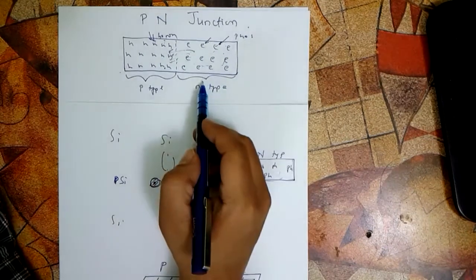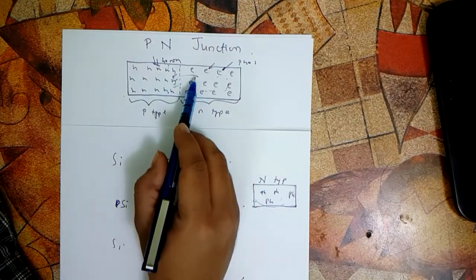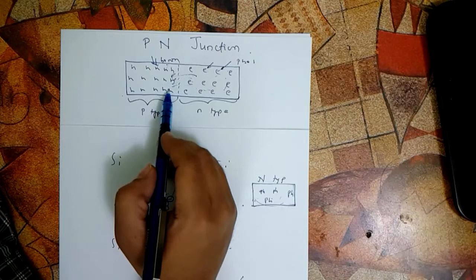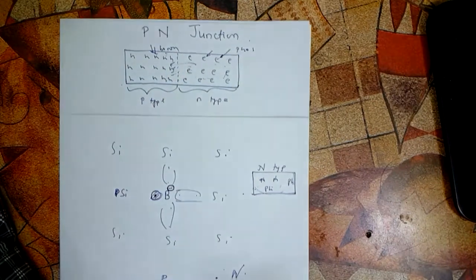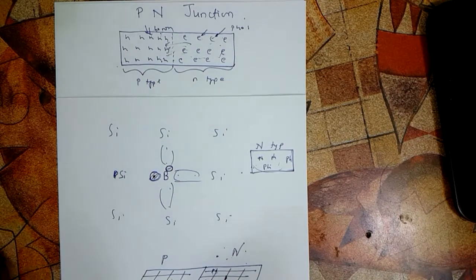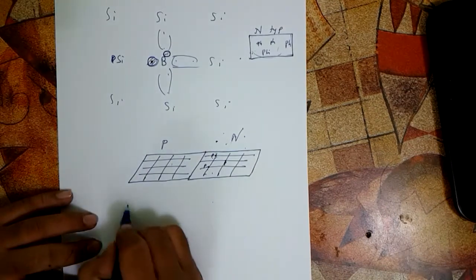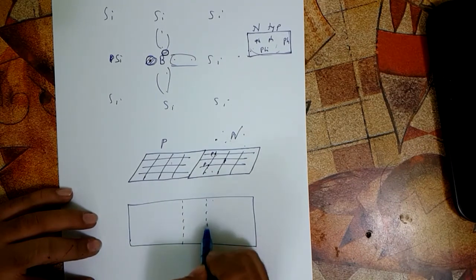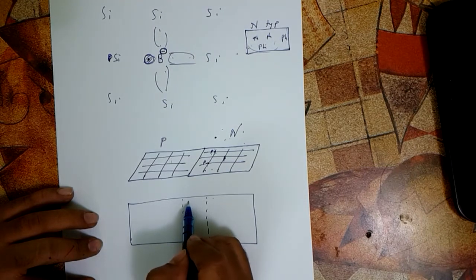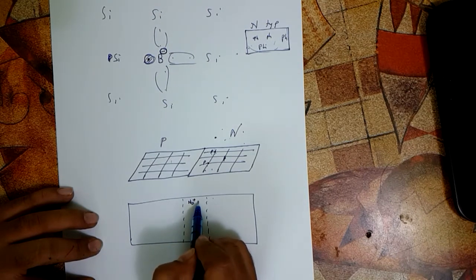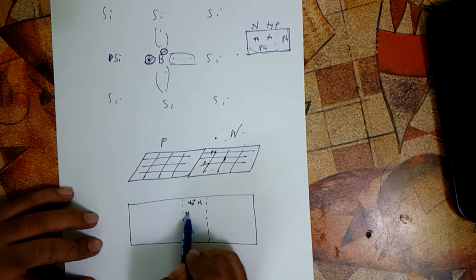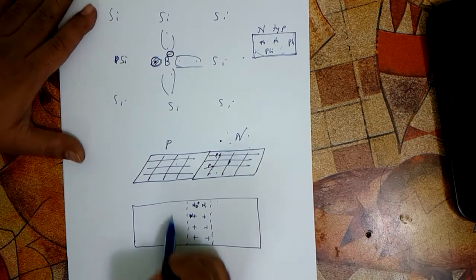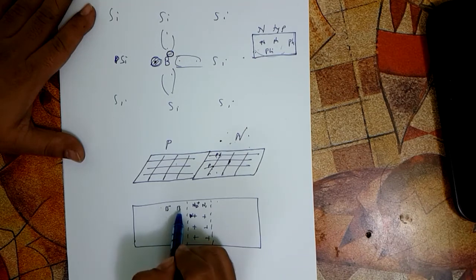But when we combine this n type with the p type, those electrons which were hovering all around the phosphorus have gone now to the p region, and once these electrons have gone, what is left here is the positively charged phosphorus. So because of the electron diffusion, we will get a region in which lots of phosphorus will be positively charged. Let's call it donor impurity positive, N_D. So there are lots of positive charges here because the electrons of the phosphorus have gone. And where have they gone? They have gone into these borons, and all of these borons are negatively charged.